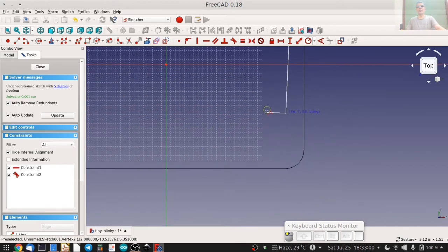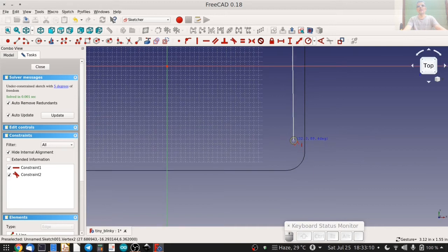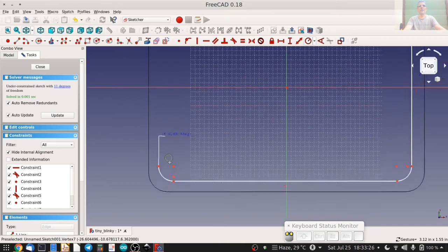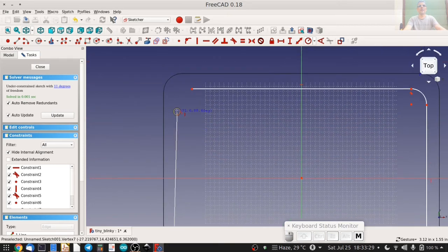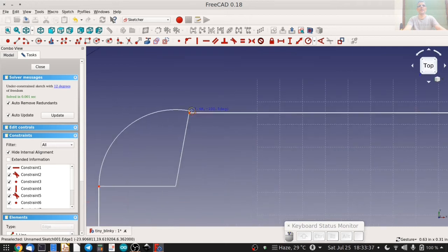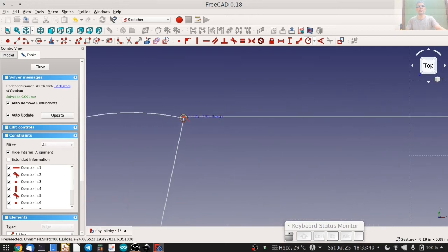Secondary click and move to, press M twice to get a vertical line like so. Then press M thrice to get the arc. Scroll again, M twice to get a line. M thrice to get the arc. M twice to get a line. And finally M 3 times to get an arc, but you want it to join up with the starting point, so make sure that when you do it the points turn yellow, at which point they are connected like so.